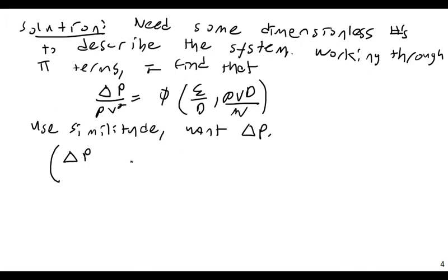They're clearly very different. Like a thing alike. Delta P over rho V squared for my model is going to be equal to delta P over rho V squared for my prototype. So I want my two delta P terms to be the same, because if I'm interested in delta P, I want them to have similitude, I should say, in terms of their dimensionless number.